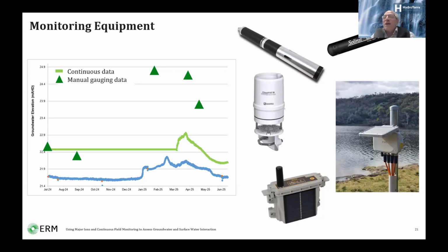I could talk for the next 3 hours about it, though, but maybe a couple of things. There are some standards out there from the Bureau of Meteorology that talk about minimum spot measurement frequencies, so depending on the application of your data, it's good to comply with those. I think the graph on the left highlights the value of telemetry, so knowing when a logger has failed or maybe hasn't been started and should have been.